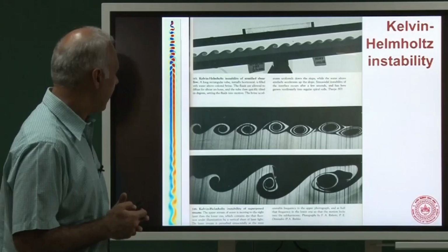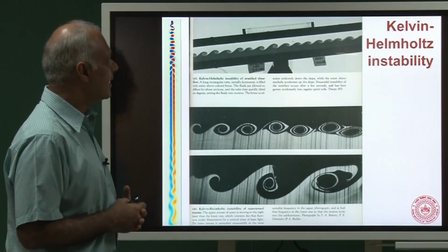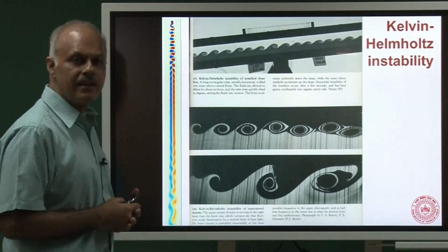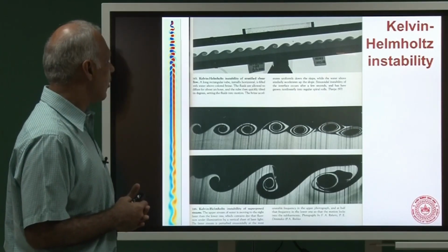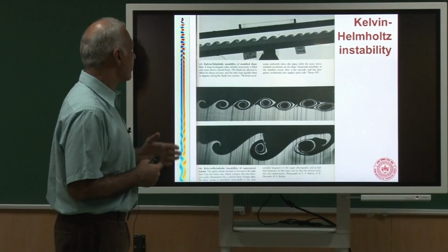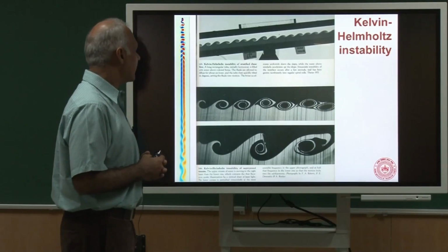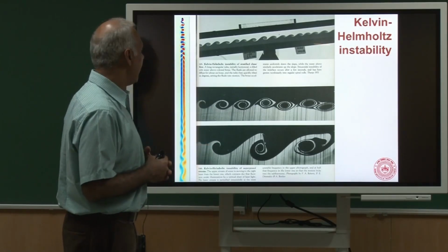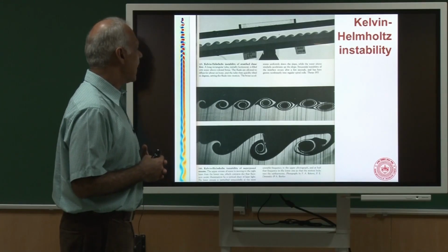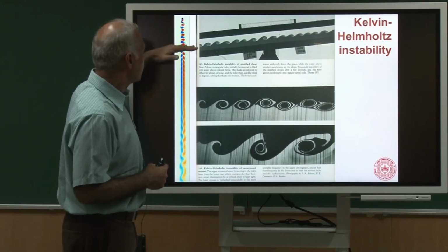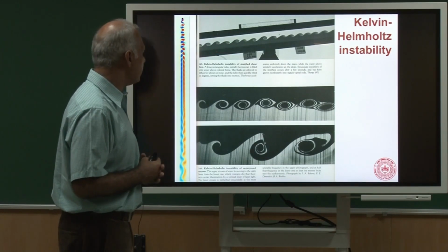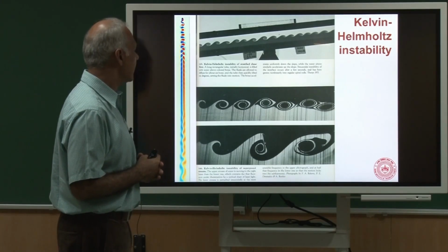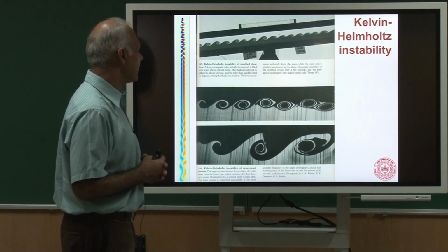This is another instability which we will talk about in the class, which is called the Kelvin-Helmholtz instability. So I will read the caption for you. There is a long rectangular tube as shown here, which is initially horizontal, and it is filled with water above colored brine. So you put salt water, and then on top of it water. Then these fluids are allowed to diffuse for about an hour, and you quickly tilt it by 6 degrees.